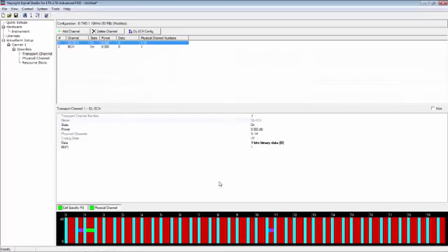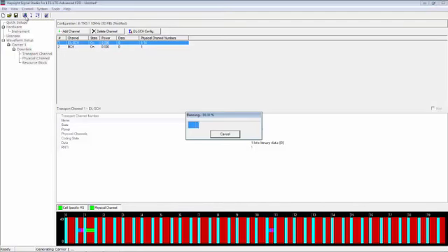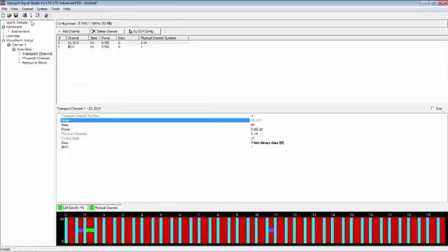So with this setup, we can then generate our E-UTRA test model 3.1 downlink signal by clicking on the generate button, and subsequently, after the signal has been generated, we can then download that signal into a vector signal generator supported by this Signal Studio software package.